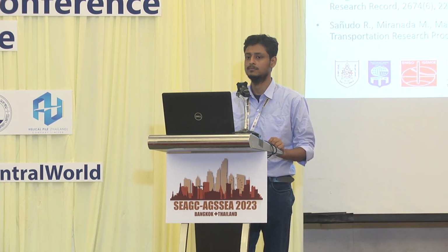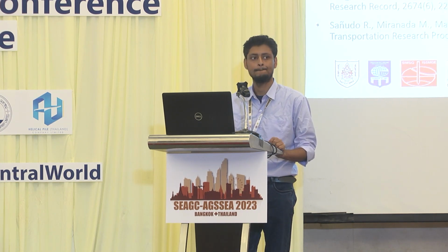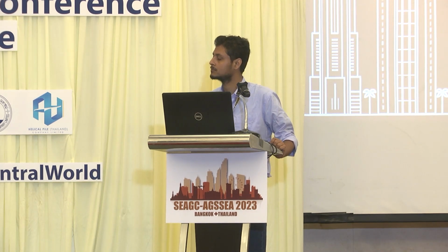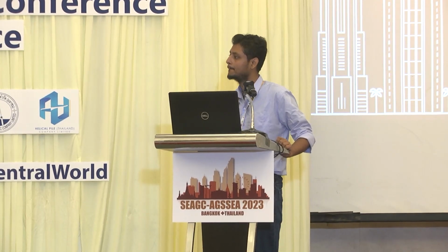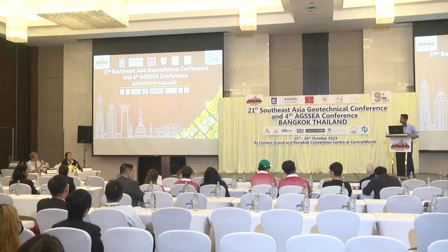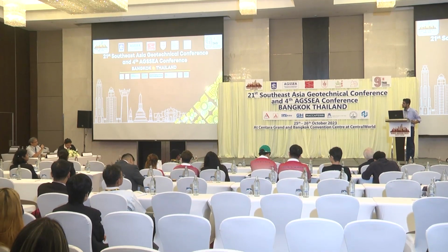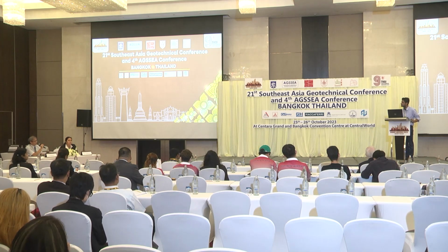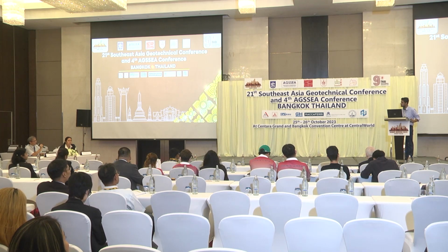You mentioned that in the future, your model is going to account for the material degradation, to model the degradation process. For OpenSees, probably you need to have a user-defined material model implemented into the program. To simplify my question: how are you going to use OpenSees to model the degradation of the subgrade material due to the traffic load? It's a moving load.